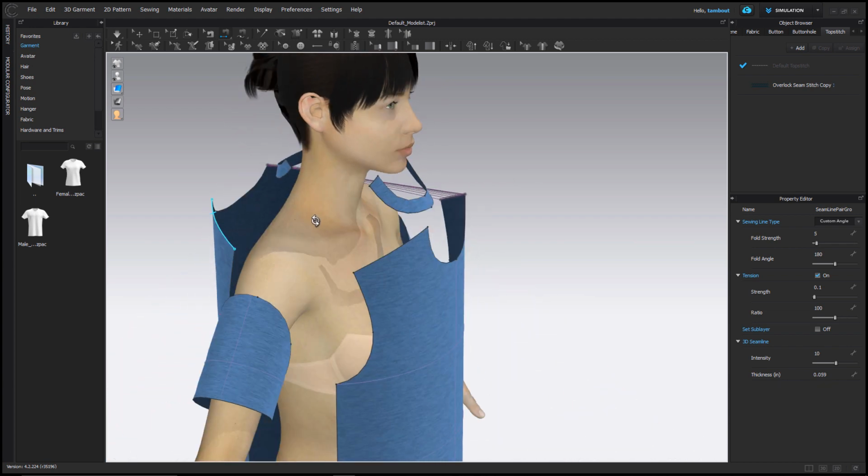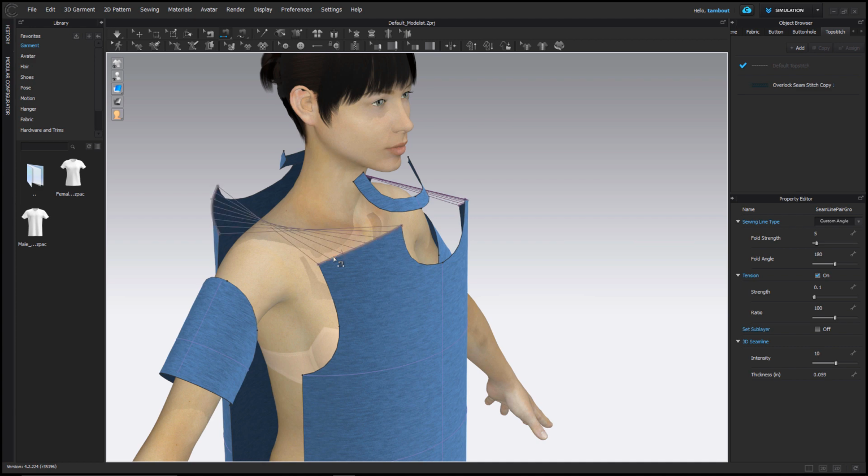Always check that your notches are aligned on segments. Here I demonstrated crossing the notches, which you can see how the sewing lines appear. To fix this, I can revert back to the Edit Sewing tool and right-click on the sewing arrangement and select Reverse Sewing.